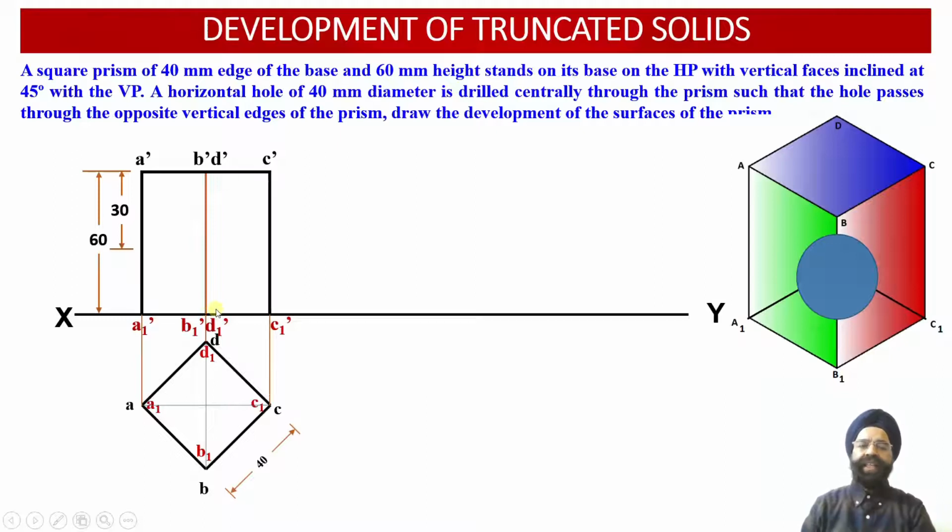Another thing we need to remember is that the vertical edge DD1, which is lying on the rear side of the solid, is going to be superimposed by the vertical edge BB1, which is available in the front side of the solid. So we should obtain the hidden line projections, that is the dotted line projections, corresponding to the rear side vertical edge D dash, D1 dash.